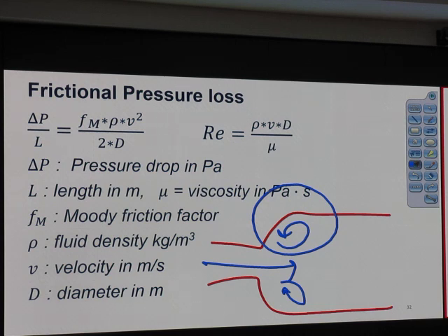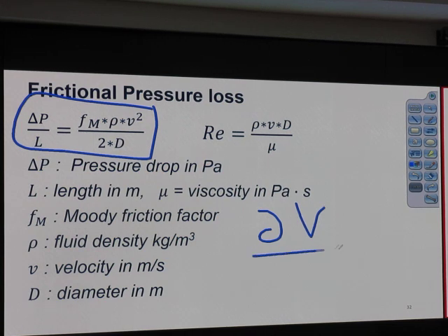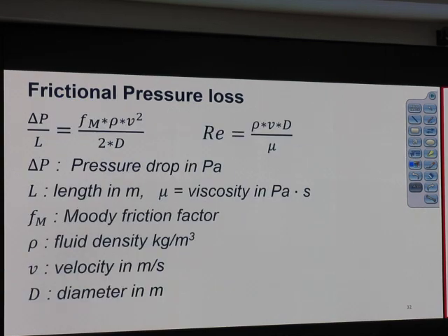So this means that near the inlet, if it is turbulent flow, the inlet shape, the inlet configuration, matters. Okay? So most of the time this equation is for fully developed flow. Fully developed means dV/dz is 0. There is no change of the shape of the velocity profile with the axial length. Got it? Maybe there's another concept that we should be aware of, which is steady state.